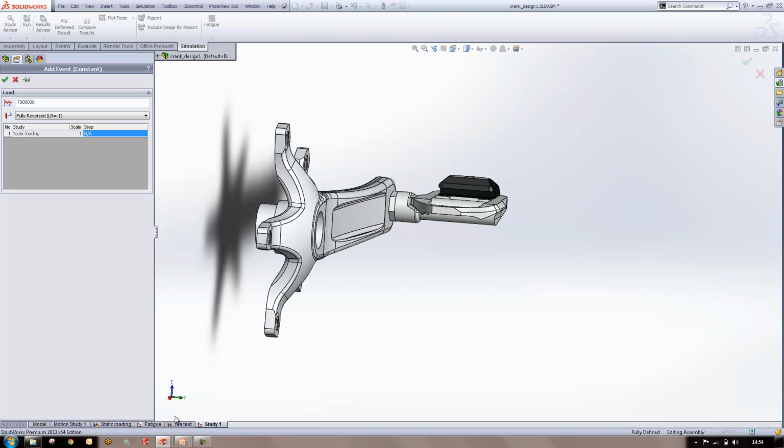So we've already set up an FEA test study, and that's the exact load that we want to incur just on a repeated cycle. So I'm going to select that, and you can see we can choose that cycle in a number of different modes. In this case, we're going to use a zero-based, so essentially the load is going to be applied and released over and over and over again. We could fully reverse it, so we could apply it, release it, apply it in the negative direction, release it, apply it, so we get a full wave.